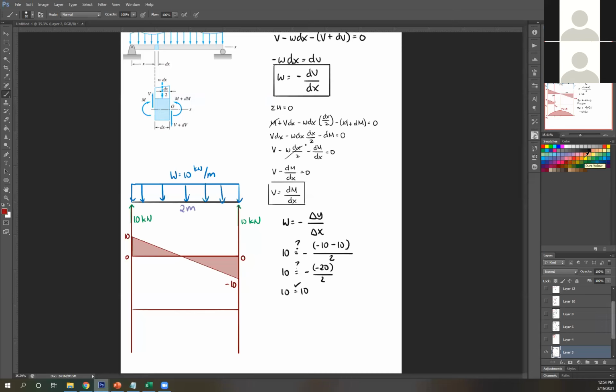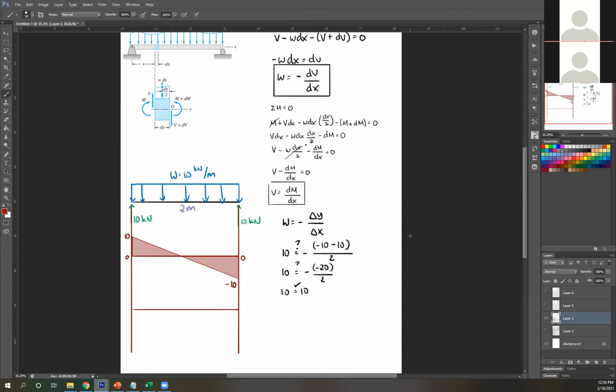Parabola. So how do I draw that? Same thing. If your area is above your equilibrium, your reference line, the slope of your moment diagram is positive. If it's below, the slope of your moment diagram is negative. Let's draw a line here to denote the change between a positive area and a negative area. So here, area is positive since it's above your reference line, so the slope of my moment diagram should be positive as well. And this is the slope of a parabola. So a positive slope would be this way. Draw it until you reach the 0 mark.